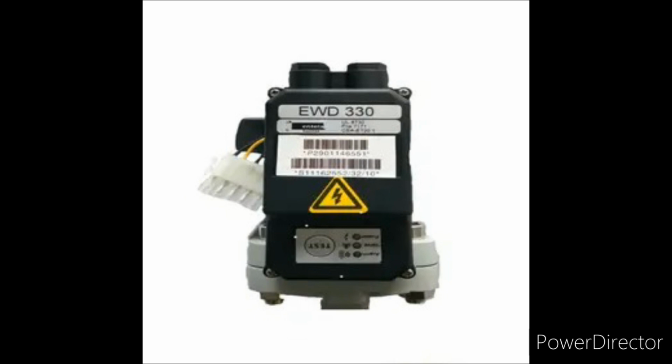To tackle these issues, automatic drain valve came into being. It is essential to have automatic drains for industrial air compressors. The water is automatically drained after each use, keeping the tank water free and eliminating the possibility of corrosion.